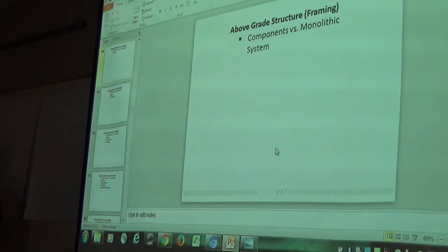So that's important to understand because there's a couple reasons. One is it helps us with the perception issue of, is this thing structurally sound? But it also brings us to the idea that you can't make the same decisions and changes on the system that you're used to possibly making with stick frame construction methods. We're taking advantage of the fact that the wall has interaction from partition walls and corners and roof trusses and floor trusses to make it structure.